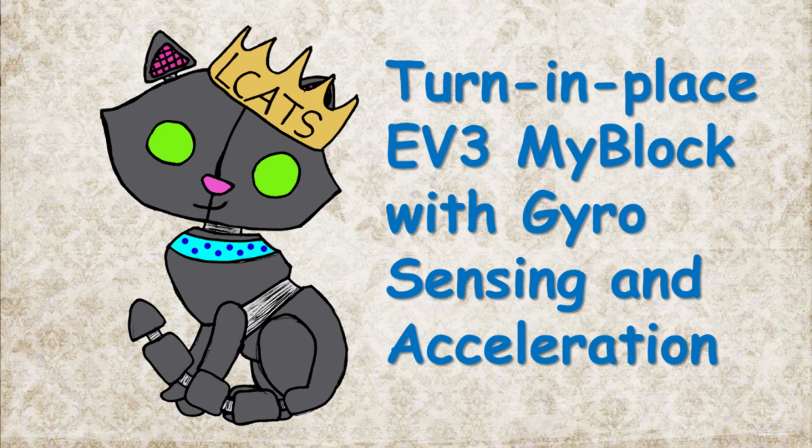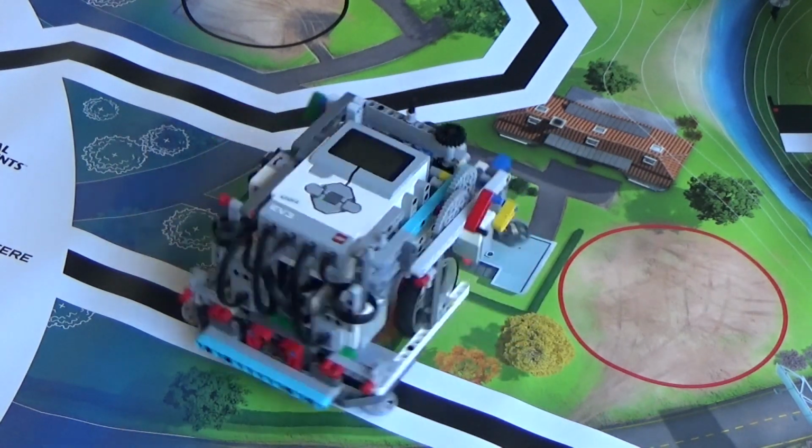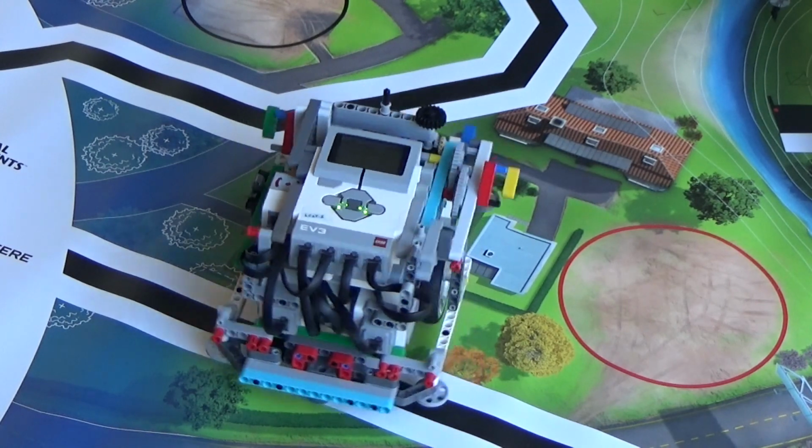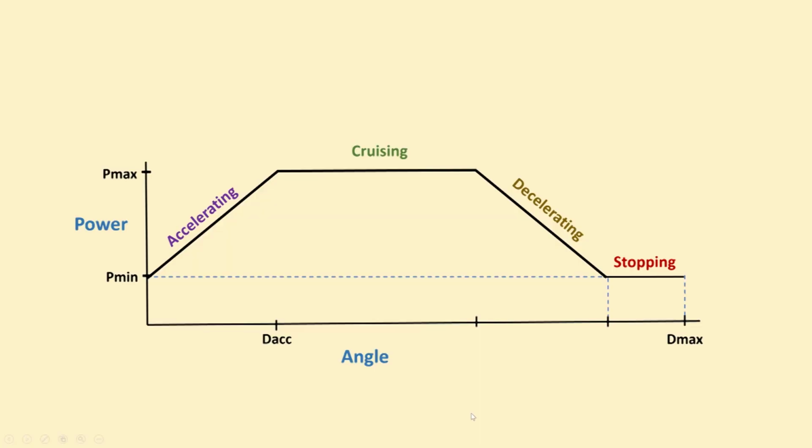Hi! In this video, I'll describe how to program a Turn-In-Place MyBlock using the gyro sensor and our team's acceleration MyBlock. The gyro sensor measures how far the robot has turned, and acceleration makes it turn smoothly. The MyBlock allows turning in positive or negative directions and turning relative to the current angle or to an absolute angle. I'll start now by describing the acceleration MyBlock.